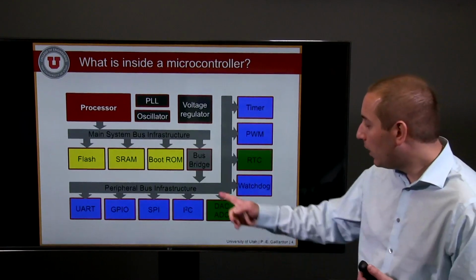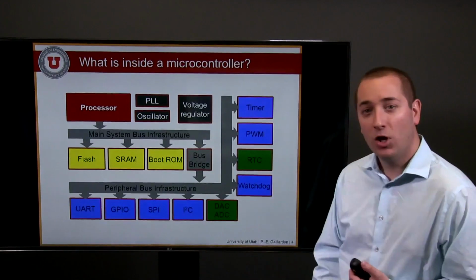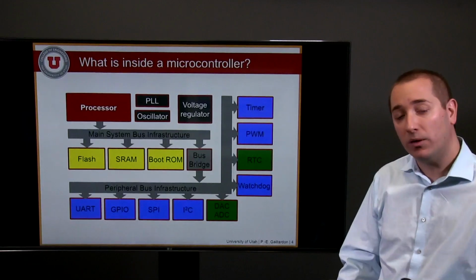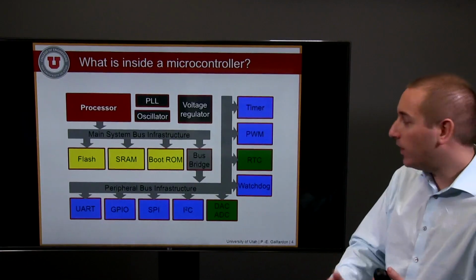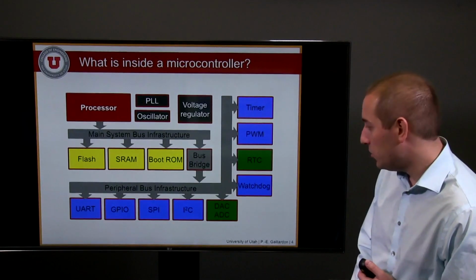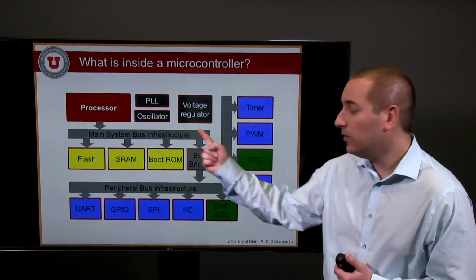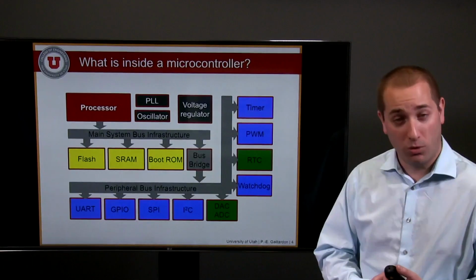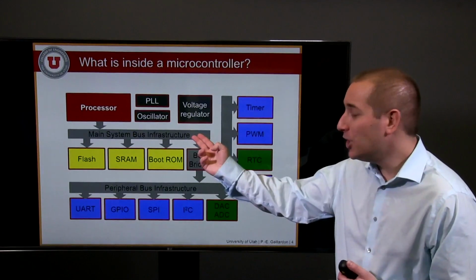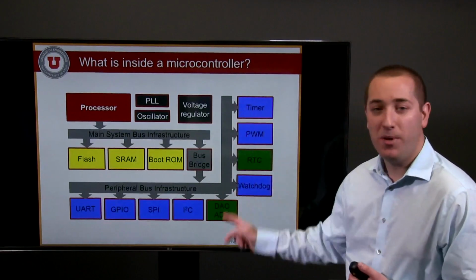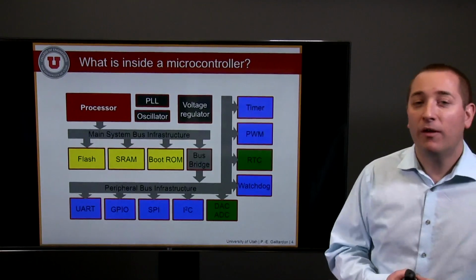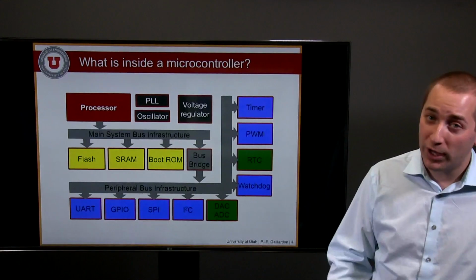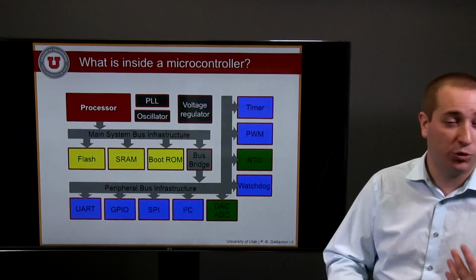Very often, those peripherals are connected not directly to the processor because of the different bandwidth requirements between the different sets of peripherals and infrastructures, but they're connected to the main system bus through a bus bridge. In the ARM world, that would be an AHB bus, and this is an APB bus. Both buses have different levels of complexity and different bandwidths and different overhead coming from the timing control and flexibility.